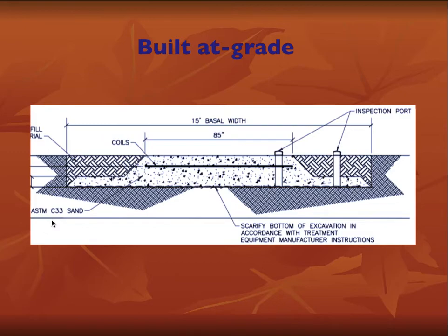Now, because these systems can be utilized in such shallow soil, if you have excess soil and the homeowner or you'd like to design it so that there isn't any kind of mound, albeit shallow, in the individual's backyard or wherever the drain field is being spec'd out, if you have the excess soil, you can dig down into the ground to make sure that you leave enough remaining soil to meet your requirements, and you can have this potentially ending at grade or flush with the rest of the land around the area.